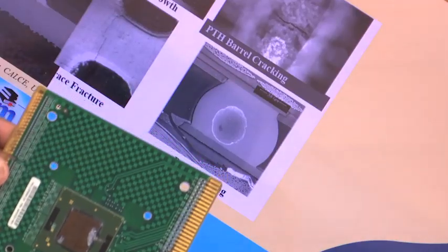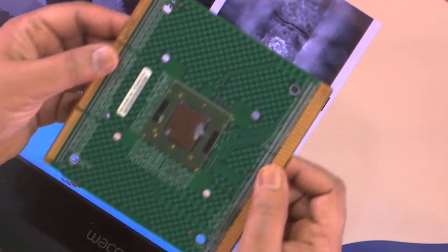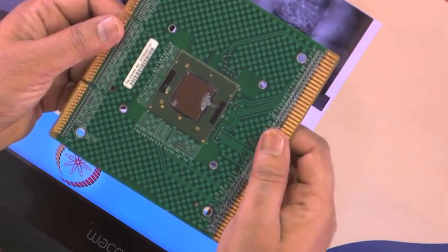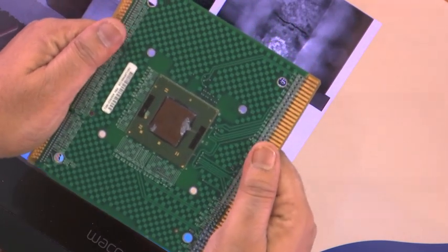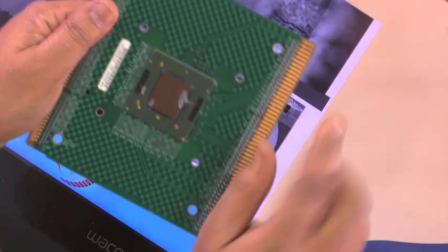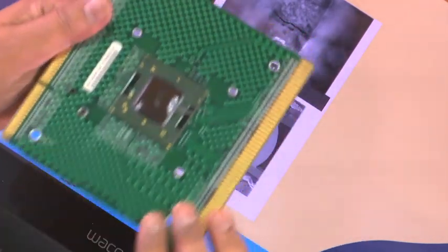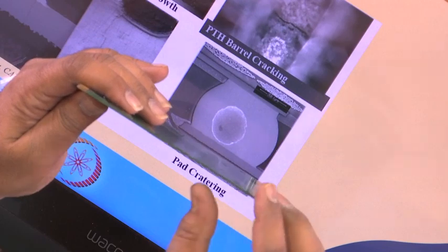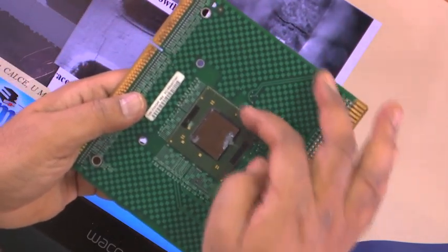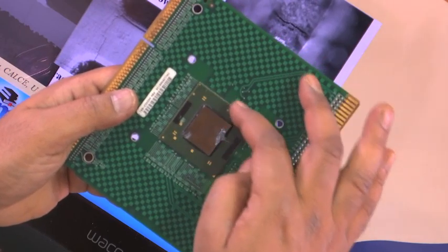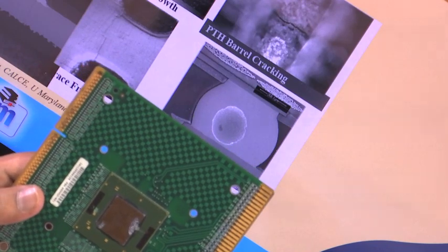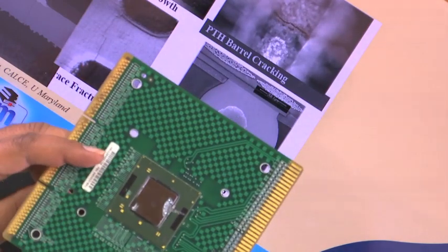Okay. If I heat it up, then the silicon is going to expand to a certain level, the motherboard much more. So, because this is held at the two ends, what will happen? In order to expand, it has to warp. It is no longer a straight line like this, but it will be bent. And with this warpage, from the end the connections may kind of open up, all right. So, this is important, warpage is another big issue.